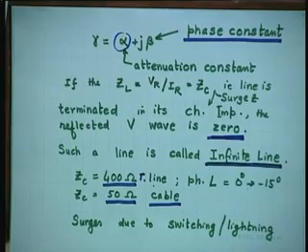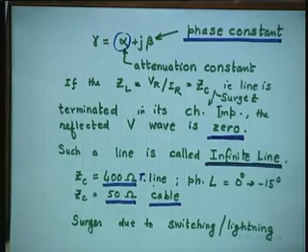Because the definition of characteristic impedance is under root L by C or under root Z by Y. C is very high in the case of cables, because the cable is right there in the ground and the effect of ground is very predominant. It is very close also, and hence this ZC is always low for a cable. Of course, we are assuming 50 hertz frequency.